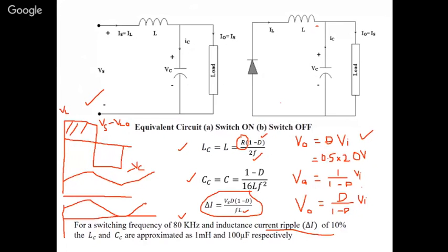In that case, when you look at the duty cycle, it is a little different. It is not so simple. I think the duty cycle is V naught divided by some I naught, the load current, and the maximum load current also it will depend on. Just go and see the equation in the Ned Mohan book, because I don't remember much, but it is a more complicated duty cycle when your inductor value is such that it is discontinuous.